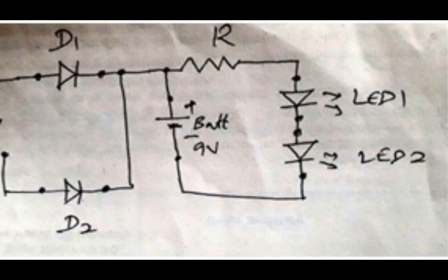See, the diodes D1 and D2 are used for full wave rectification. Actually, the capacitor filter is not shown in the circuit for simplicity, as this is the first circuit we are going to discuss. If an AC source is used, then the battery should not be connected.